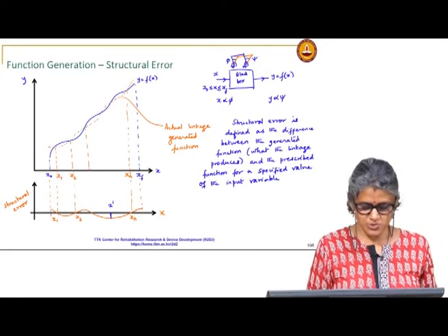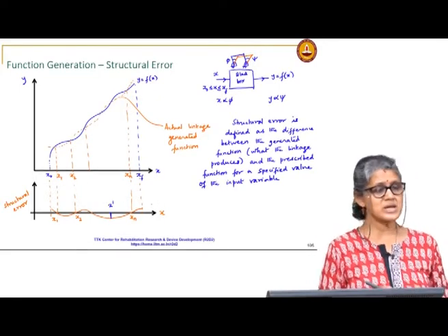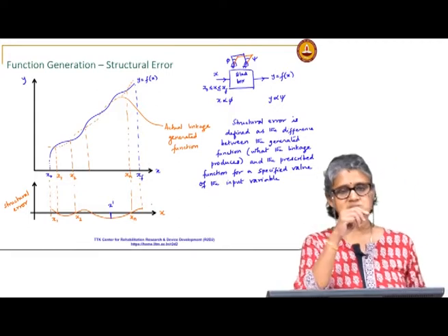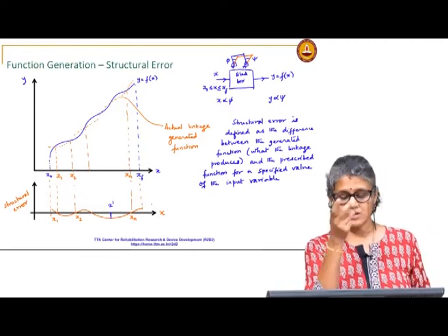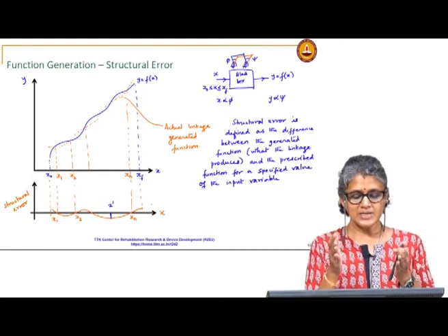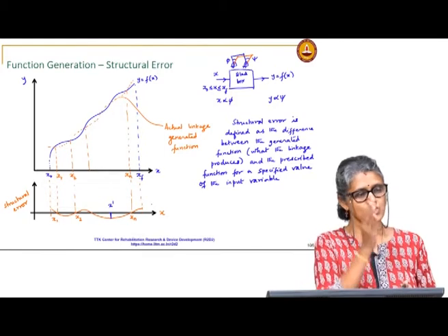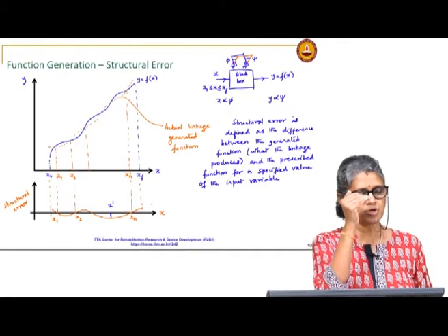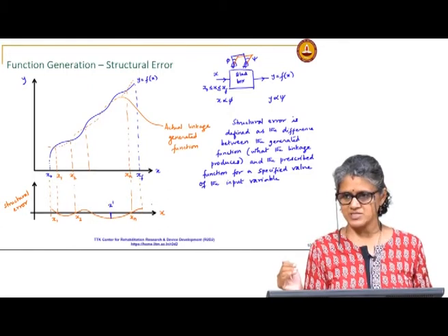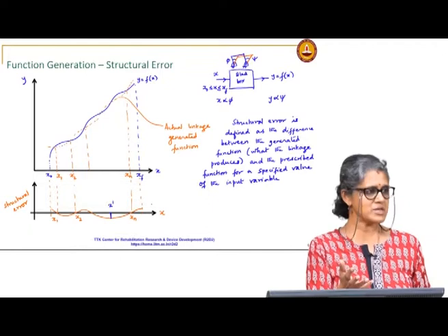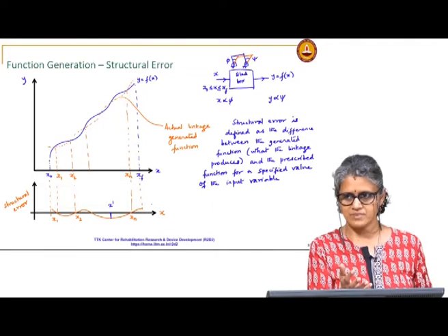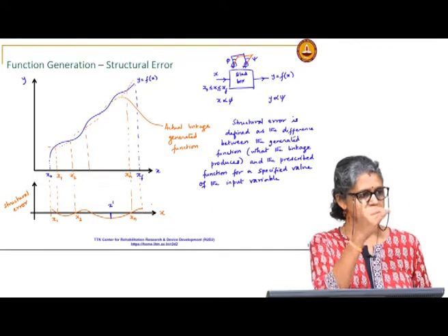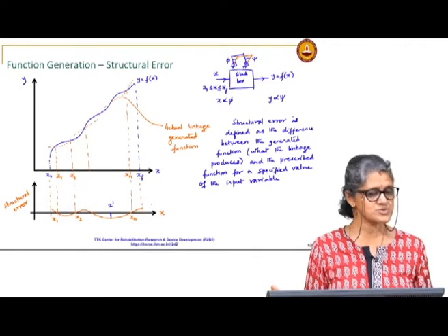So, how do we choose these? Typically, you want to choose the precision points. In motion generation, if you are only looking at specific positions, then those will be your precision points, the configurations you choose.